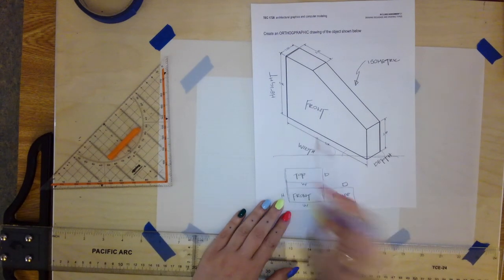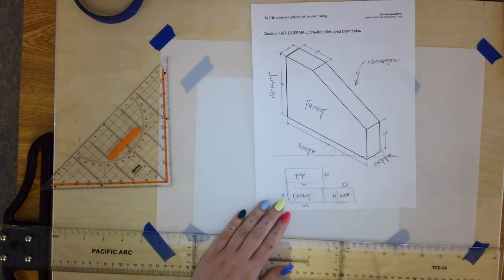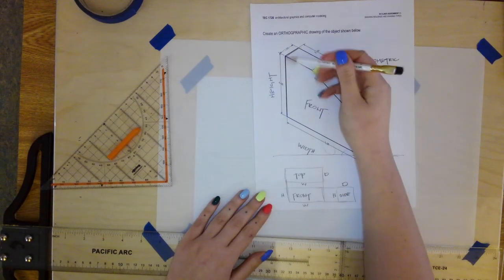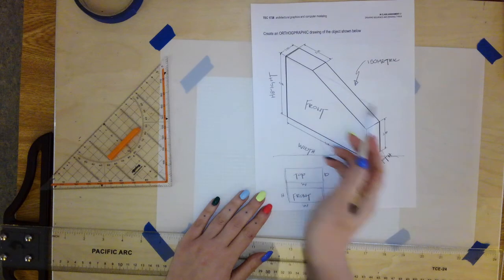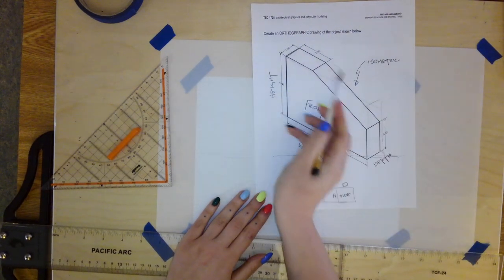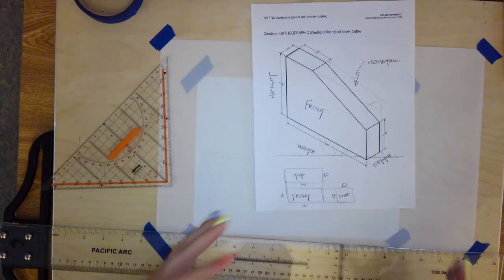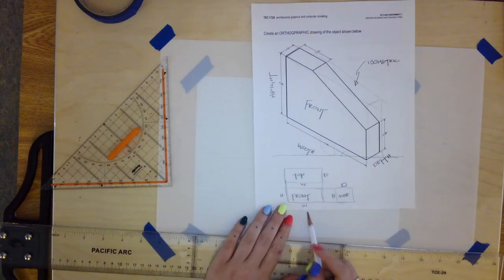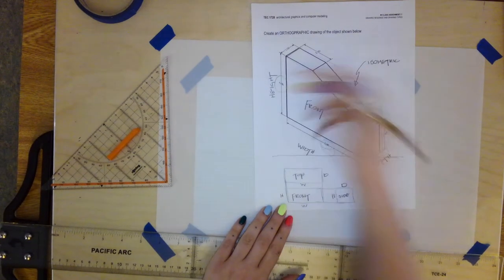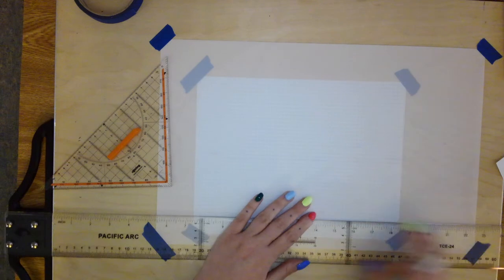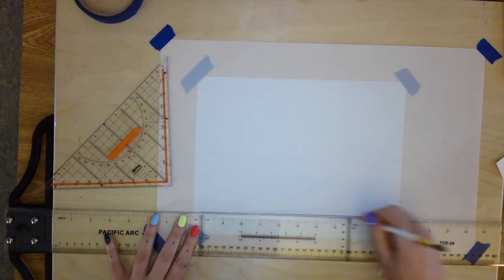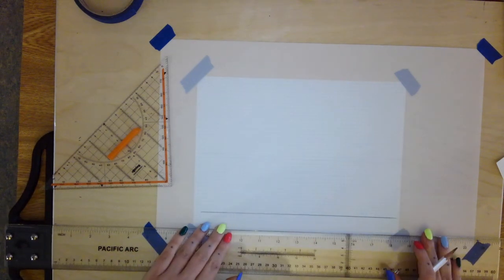So based on the information I have for my front view, I'm going to use what's called the bounding box technique, where I'm just going to draw an overall box. If this thing was essentially a big old slab of marble, and there was just a whole big box in it, what are my overall dimensions for my front? It has an overall width of 6 and an overall height of 4. So just picking somewhere in the bottom to start, I'm going to draw a light guideline out.